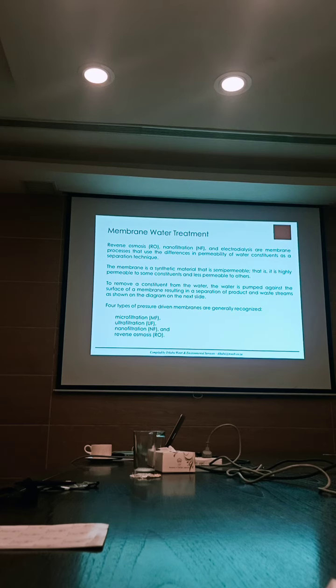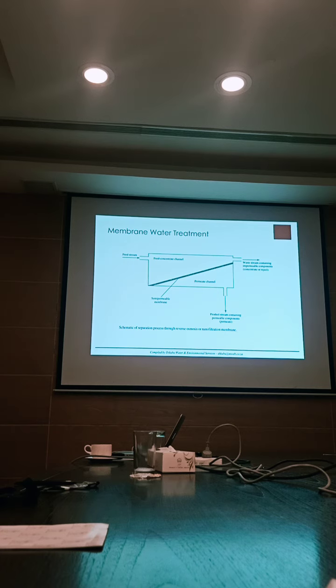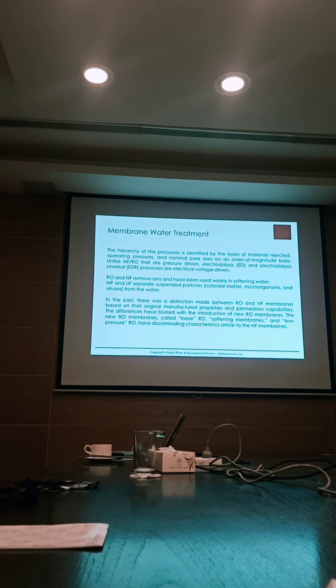The point I'm trying to make, maybe it's not directed at you guys because you've got some knowledge, is that people often just apply RO because they only think of RO as a membrane option. They don't realize that there are other membranes available for different applications. And the RO membrane sellers don't always tell them that because it's more expensive to put in an RO membrane. And so I see a lot of RO being applied where it's not necessary. So that's the concept. I think you're very familiar with that.